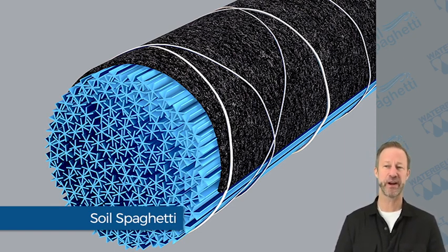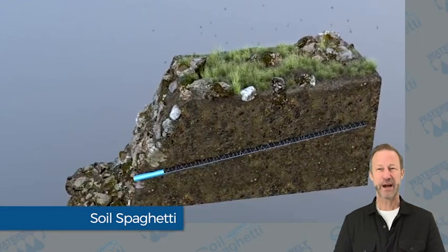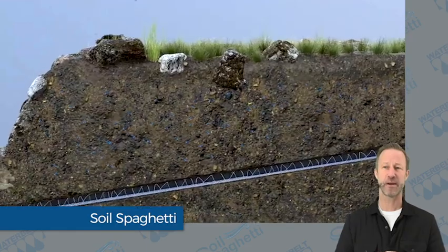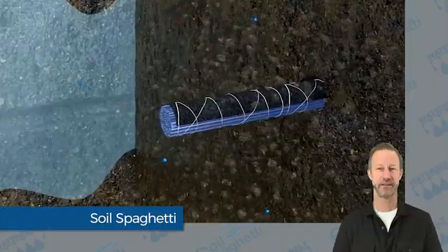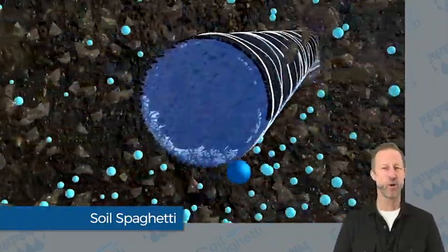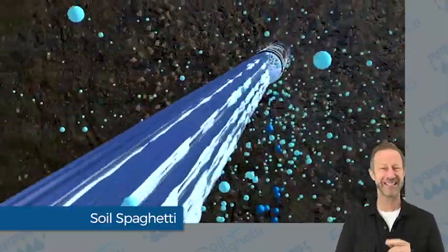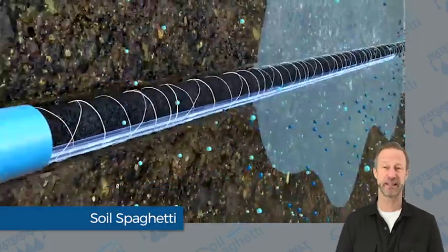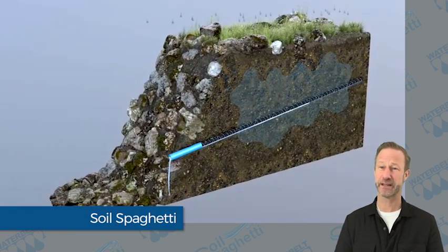It is the only pipe drainage product which can collect water without having soil particles enter the drainage system. It can be a standalone drainage solution, or it can be cut to any length required for an effective solution. Spaghetti pipe is a practical repair method for existing retaining wall drainage, as well as a fast and easy solution for slope stabilization applications. It functions similarly to Waterbelt, horizontal drain, but the collected water must discharge along the full length of the pipe, and is not as rigid as horizontal drain during installation. Spaghetti pipe is recommended where the required length of the pipe is less than 5 meters.